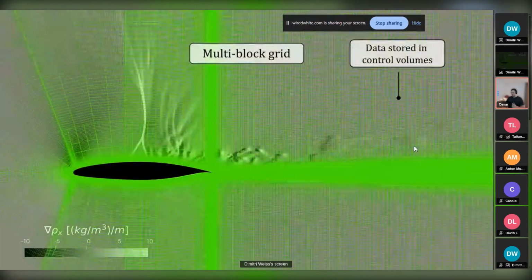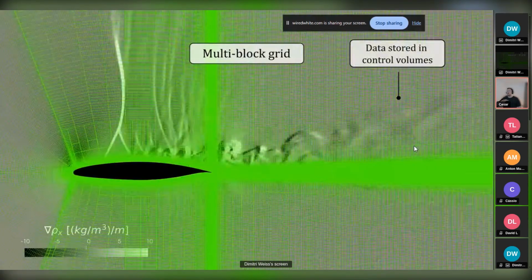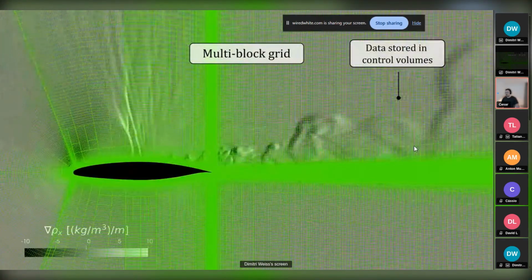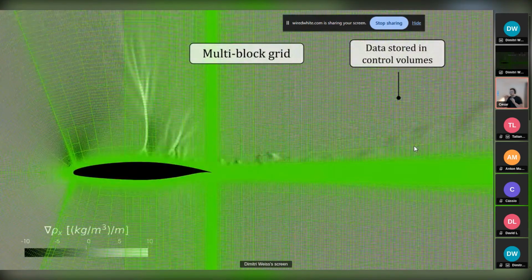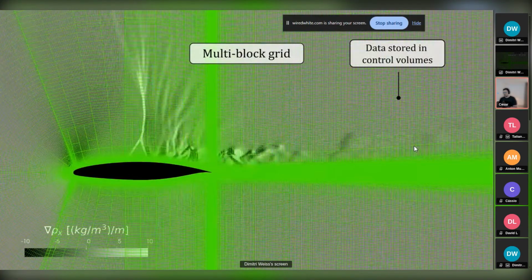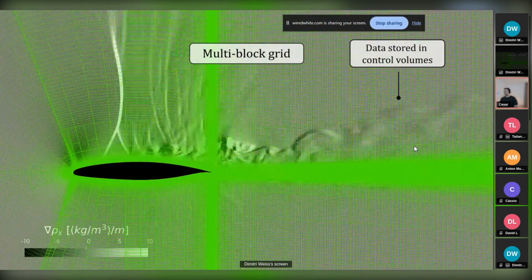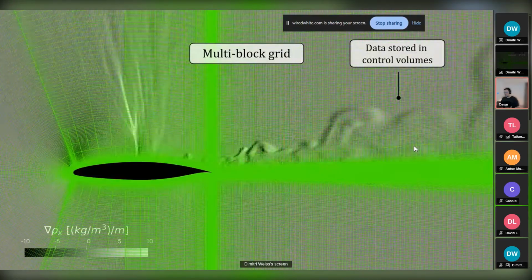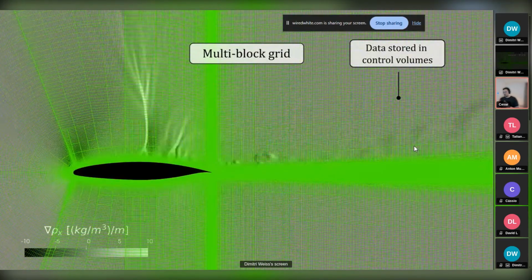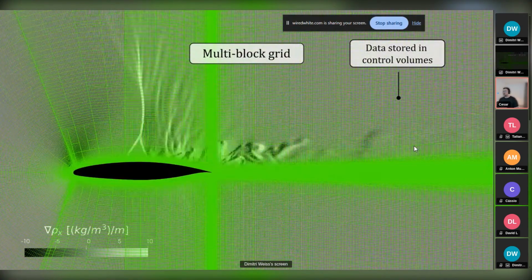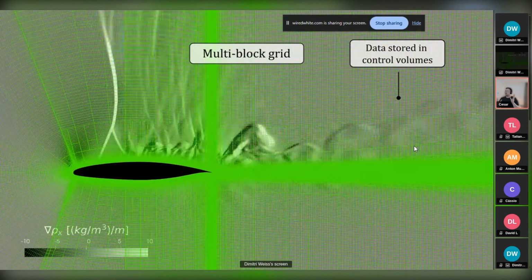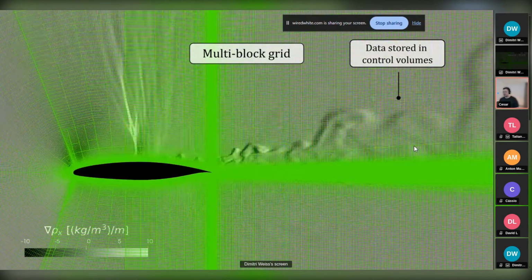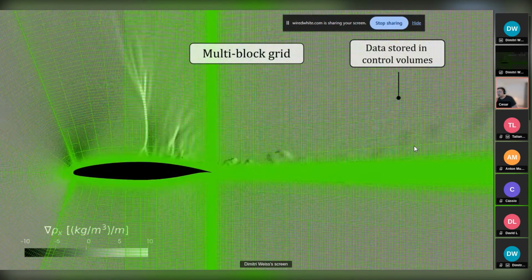And this is exactly where computational fluid dynamics excels, because we are modeling all this numerically. We have access to all the data in the flow, because we have discretized our whole domain into small control volumes, and then we can access the data exactly. However, we are using models, and we need to know the limitations of each model, and therefore we need a strong interaction between experiments and CFD in order to really understand the real dynamics. Can you go to the next slide?